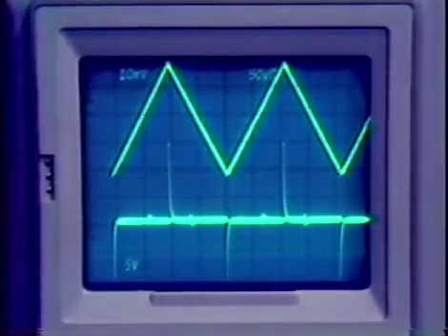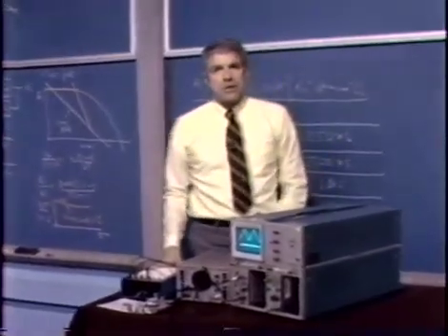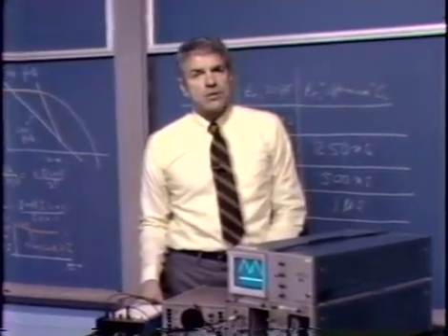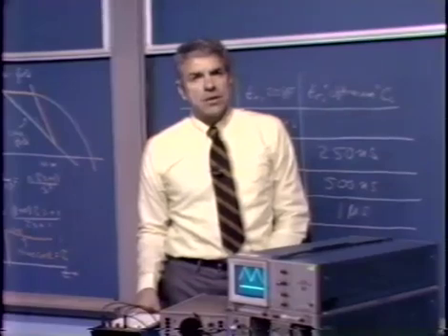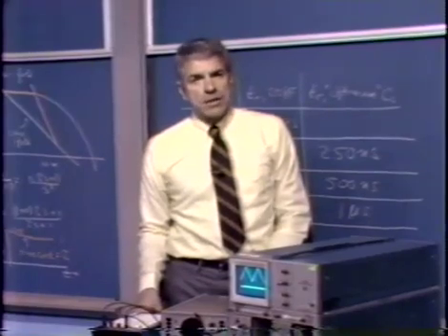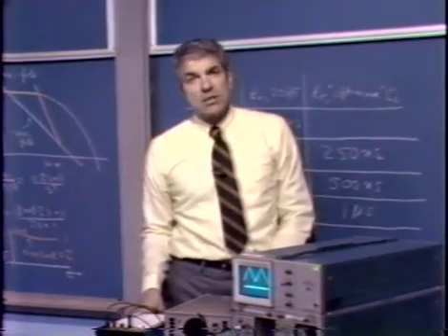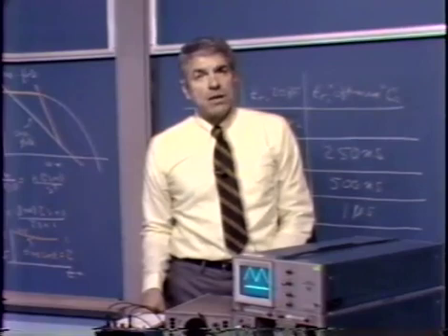Does that make sense? Well, here we have changed the amplifier so that over a wide range of frequencies, its open loop transfer function falls off as 1 over S squared. In other words, over a wide range of frequencies, the output is the second integral of the error signal, or correspondingly, the error signal is the second derivative of the output signal. We have a series of ramps at the output, a triangle wave at the output. Why, we'd anticipate that the input signal would be the second derivative of the triangle wave, or a series of impulses. Of course, they're not perfect impulses.